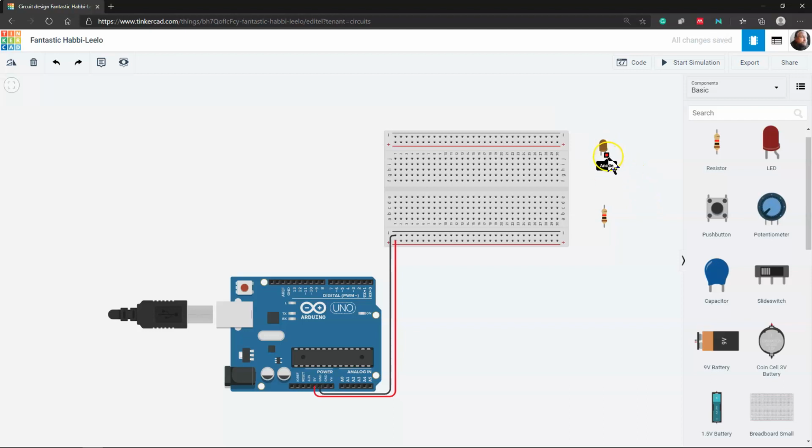It's off. And you remember right here, looking here, you have the cathode, meaning that's where the negative has to be attached, and you have the anode, that's where the positive has to be attached. Because again, this is a diode, which only allows current to flow through it one way, going from the anode to the actual cathode itself. If you hook it up the opposite way, positive here, negative here, this light will not turn on.